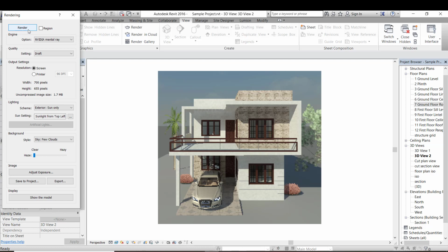In the render quality option, we can change the quality from draft to best. Draft option provides a very fast render for us to check if everything in the view is correct. For print quality images at least, a medium quality is needed. Keep in mind that as the quality increases, the render time also increases. We can use a DPI of 300 to get high quality images. When we change the DPI, the file size also increases and this also affects the render time.